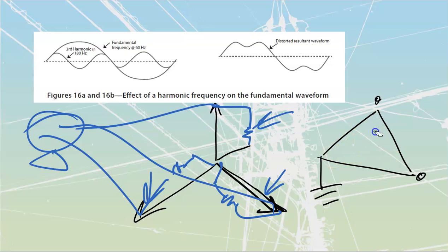I don't know if you remember those phase lights that we had for delta at the beginning of the year, but your motor is going to act the same as we had for those phase lights. If I've got a delta-connected system that has a corner ground on it, I'm going to have my Y-connected motor, and we'll just pretend that that's the Y connection, that's the little center point over there. This is basically what my motor is going to be doing. It's going to be going across from line to line like that, which means these two phase sections are going to be stretched out immensely. Massive amounts of voltage over top of them, and they're going to have differing amounts of current going through them, and this as well is going to have a differing amount of current as it translates out of that line. It's just all around bad for these motors.